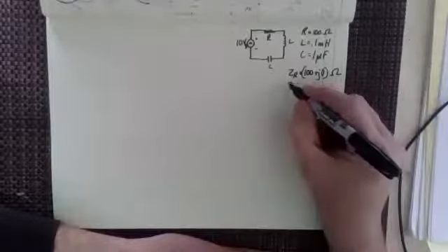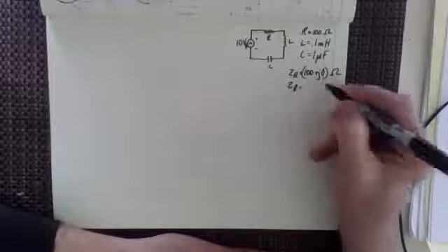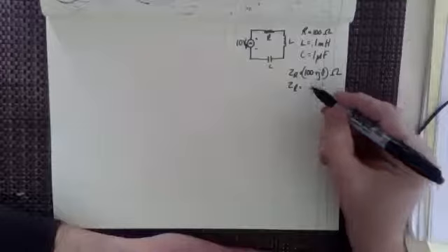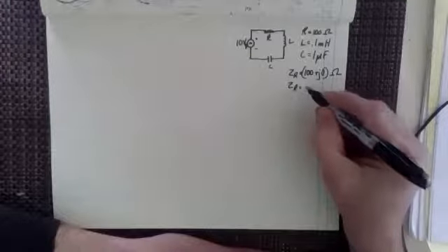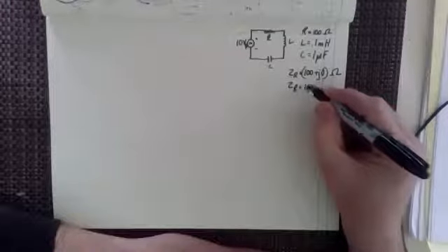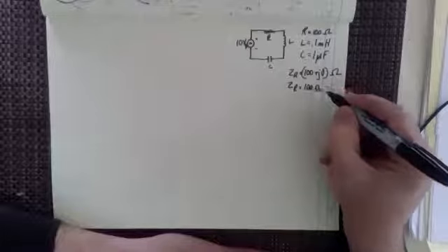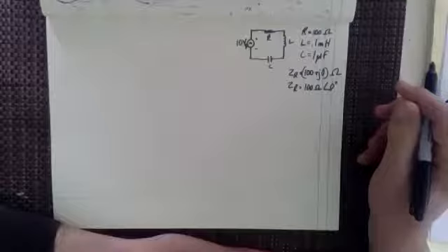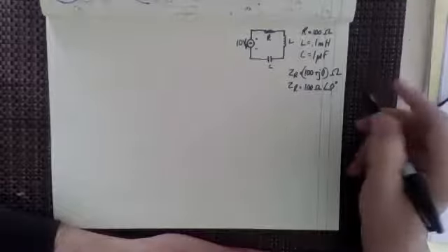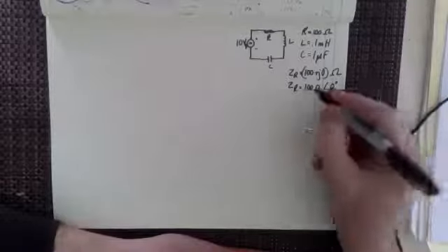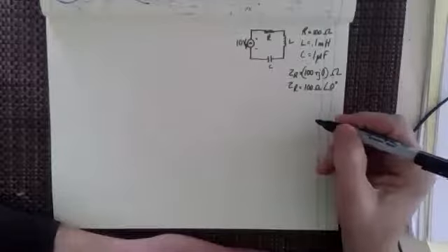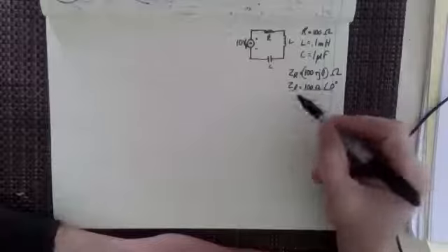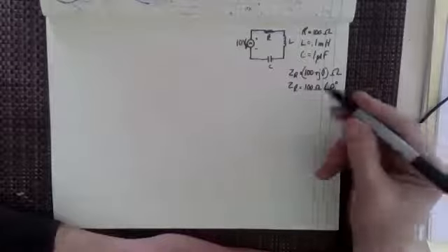And if I wanted to write that in phasor form, because we may be multiplying and dividing over the course of this lecture, I would say that would be 100 ohms at an angle of 0 degrees. I don't think anybody should be surprised about me writing this in the a plus jb rectilinear complex number notation, or writing it in phasor notation.